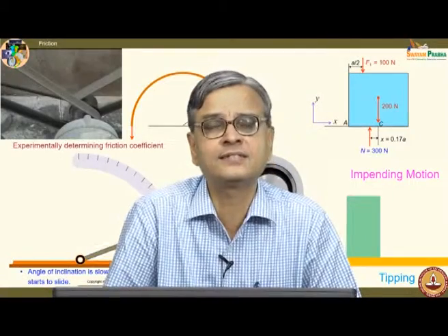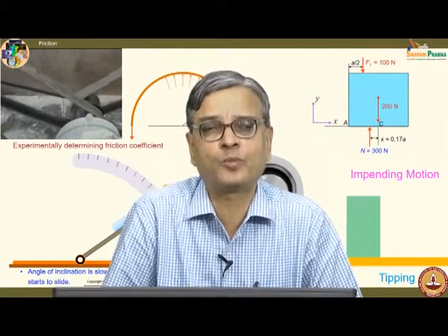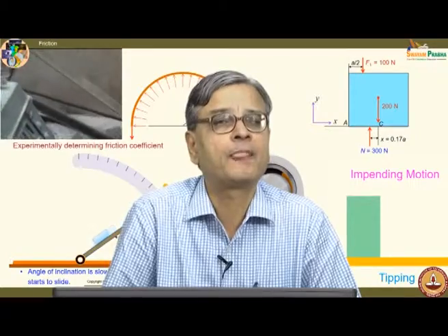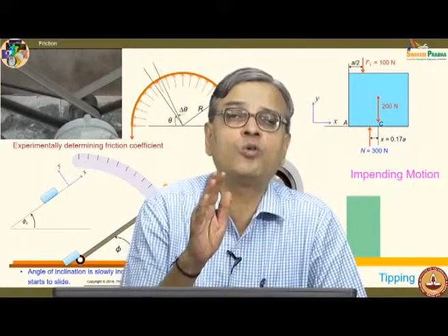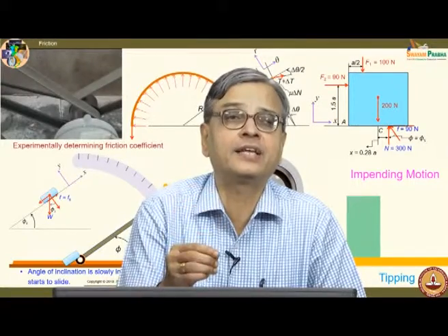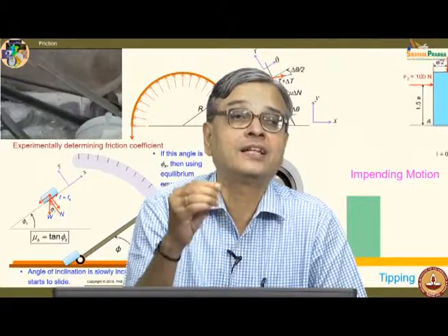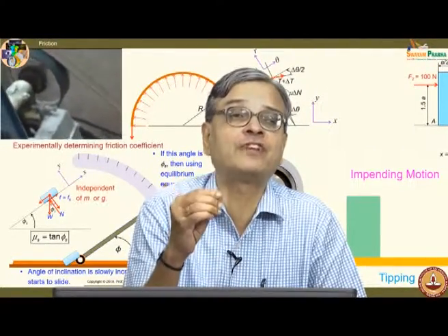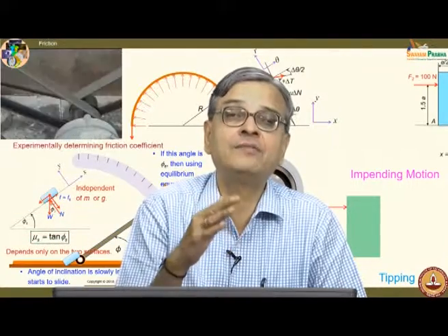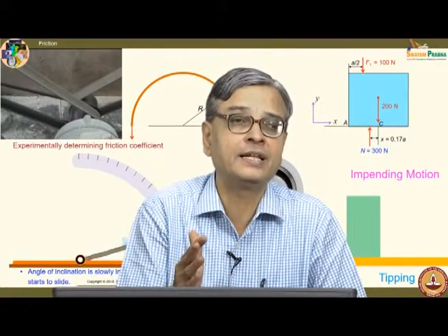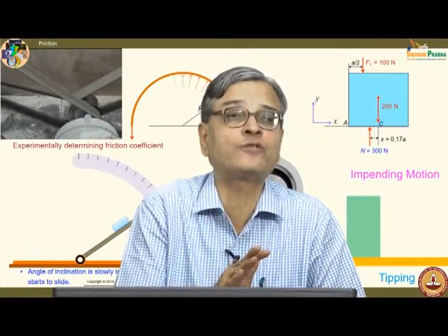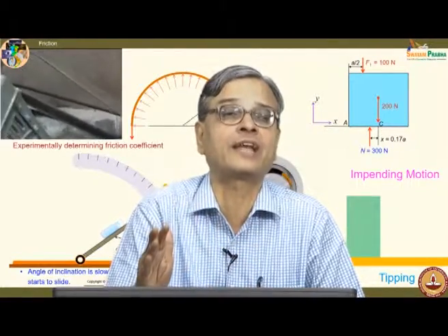So, in this class, we have solved a variety of problems dealing with friction. We have listed out a systematic procedure on how to approach a problem dealing with friction. It is worth spending a minute investigating the direction of the frictional forces developed. Then investigate whether the motion is impending. Then only replace the frictional force as mu times the normal reaction.